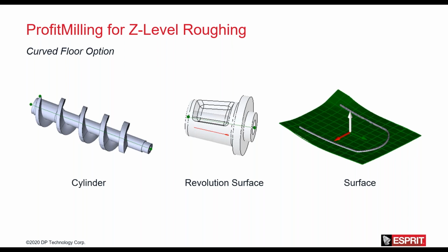If your drive entity type is set to revolution surface, you're building a surface from a profile by defining the profile and the 2 points for the surface center line. You can choose whether the revolved surface is machined on the outside or inside by choosing an option for internal or external machining.